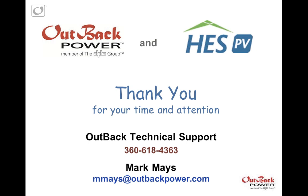I mean, obviously, this can take some modification, but it's not quite as bad as you might think. You're just going to move where you would tie into the main service panel. You would take that L1, L2, neutral and ground, and you would just move that into our load center. Then you'd have to have new lines that would go to your service entrance from there. And then you would have a critical load center that would feed.